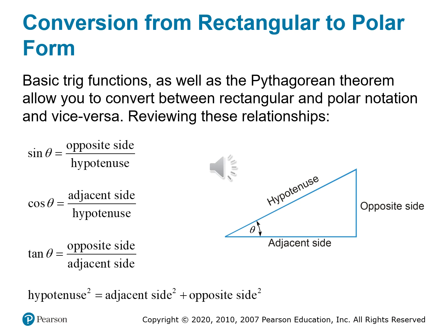This lets you perform operations like multiplication and division more efficiently. From polar back to rectangular, you reverse the process, where A is equal to C cosine theta, B is equal to C sine theta, and then write it as A plus jB. It's exactly what we did when analyzing current and voltage in RL circuits earlier in our podcasts, especially when calculating power triangles or understanding phase shifts, if you remember that.